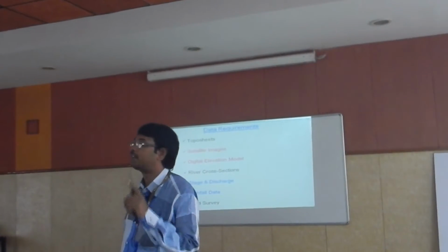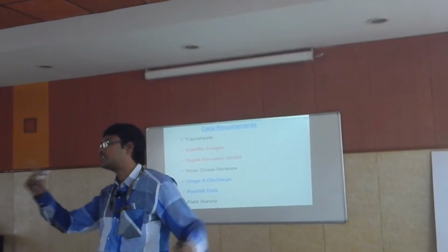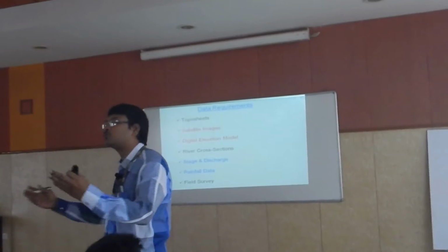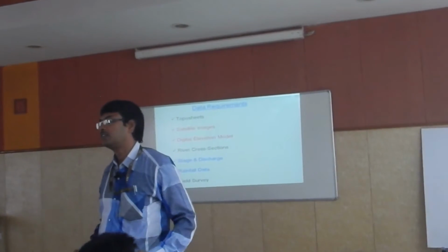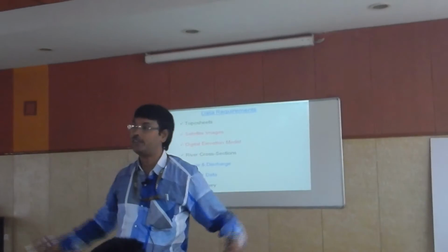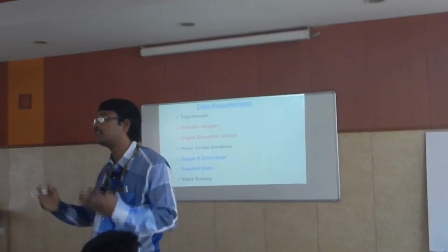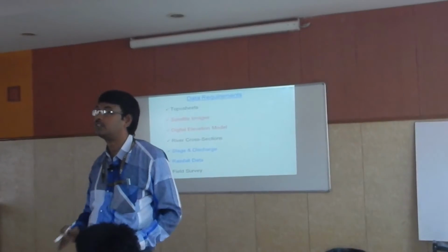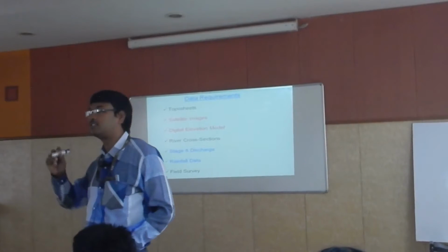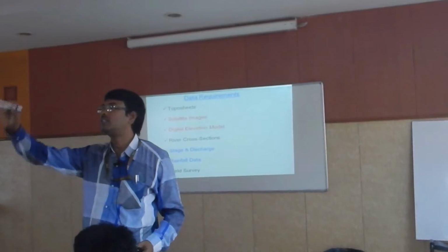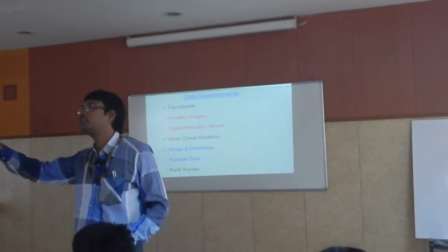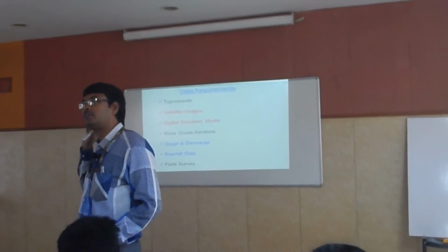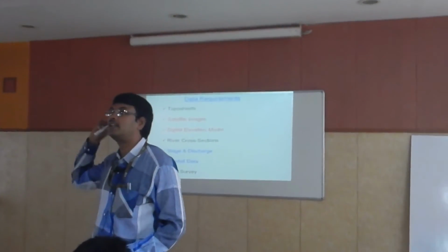Is it possible to survey the cross section in one day? Suppose it is 200 meters, you have the flexibility to go and do the field survey. But if the river cross section is 4 kilometers, is it possible to complete the survey of that particular cross section in one day? Obviously, you do not have the flexibility. But here, you have the flexibility. Simply make one line, and automatically it will provide the elevation information. That means how the river cross section is located at that particular place will be provided with the help of this digital elevation model.